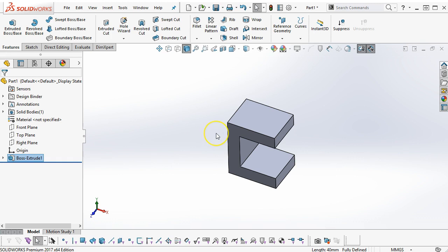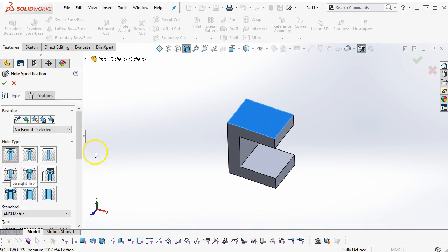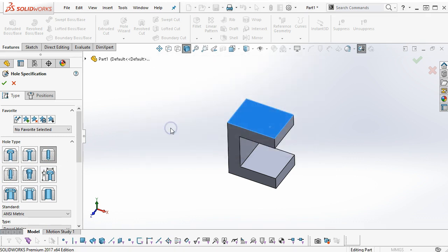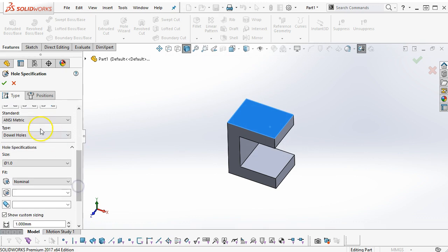Next decision is the hole through the part. This is pegged together. When we do the simulation or the assembly, we may see that the rotation on this, we want to choose a different fastener. If there's a possibility that we would go from a through hole, a clearance hole, to a countersink, to a counterbore, to a threaded hole, then we would want to use the hole wizard. So for this, we'll go hole wizard, and we can stay with the simple. There was a previous value, so it can go ahead and reset.